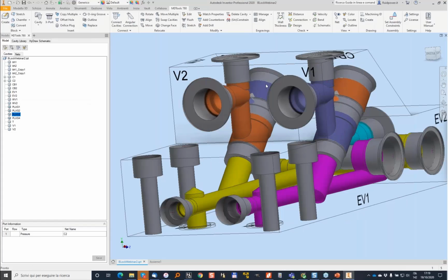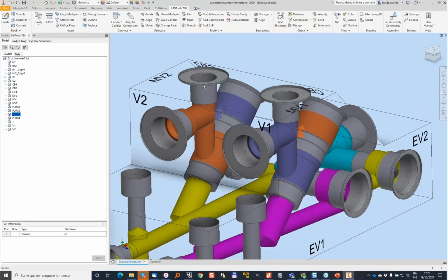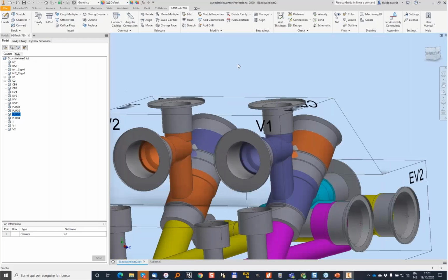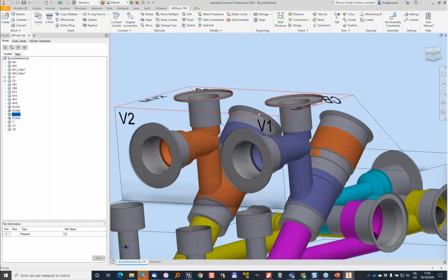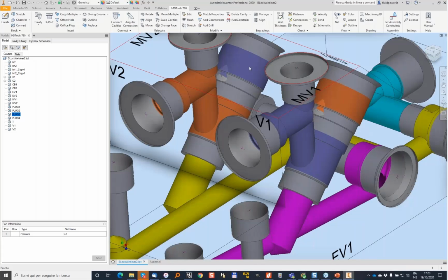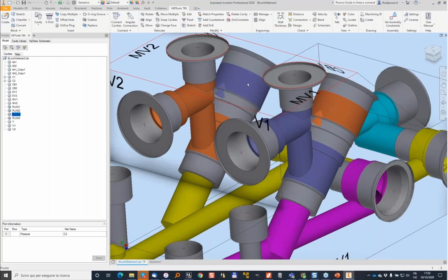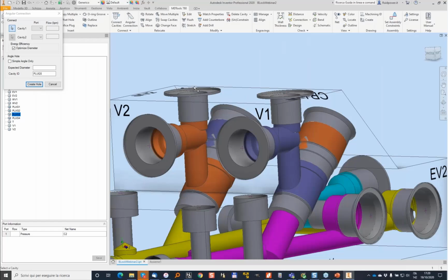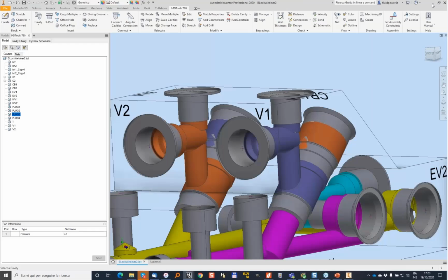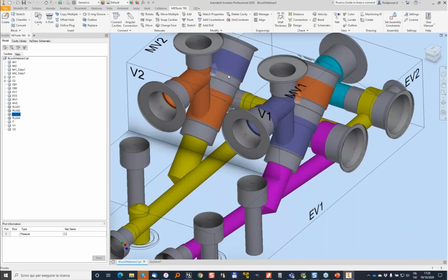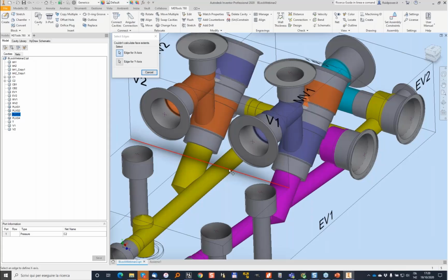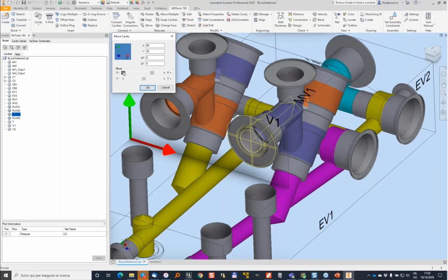Let's try to make some strange intersection. So I want to make a drill that is connecting the purple with the other port 3 of the counterbalance valve. So I want to make an angular connection between this valve. Sorry, this is getting a handle exception. Let me move slightly here. I want to move this cavity slightly to the left.